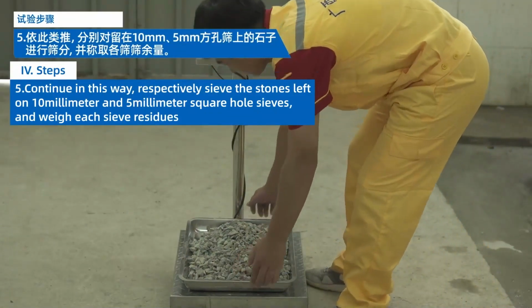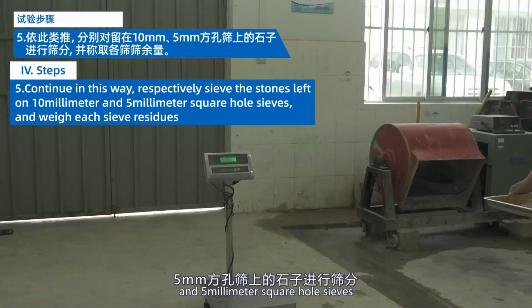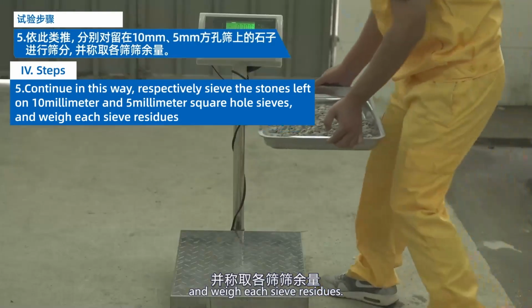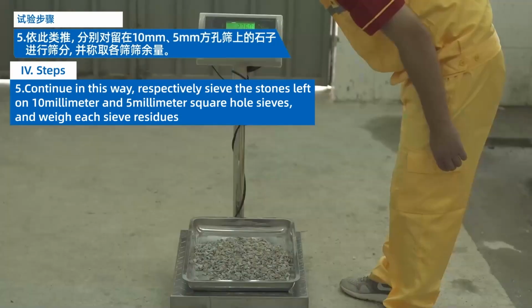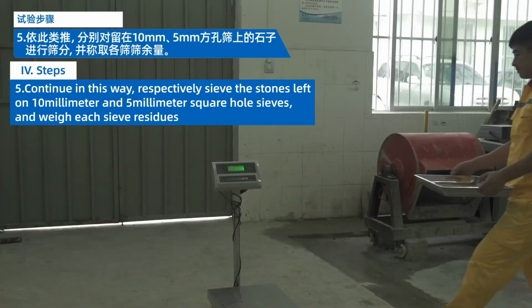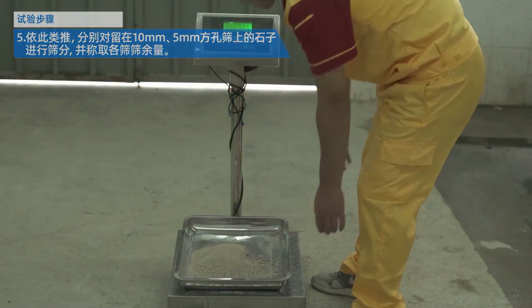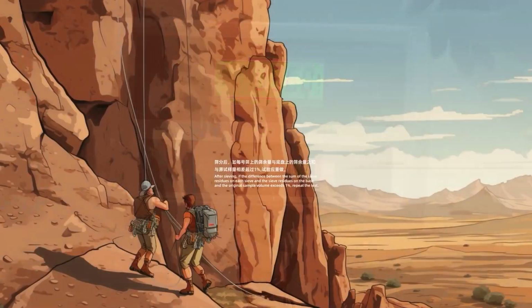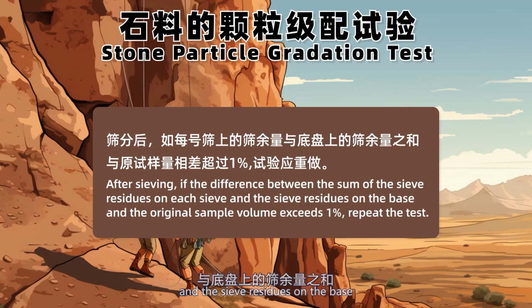Continue in this way, respectively sieve the stones left on 10 mm and 5 mm square hole sieves, and weigh each sieve residue. After sieving, if the difference between the sum of the sieve residues on each sieve and the sieve residues on the base and the original sample volume exceeds 1%, repeat the test.